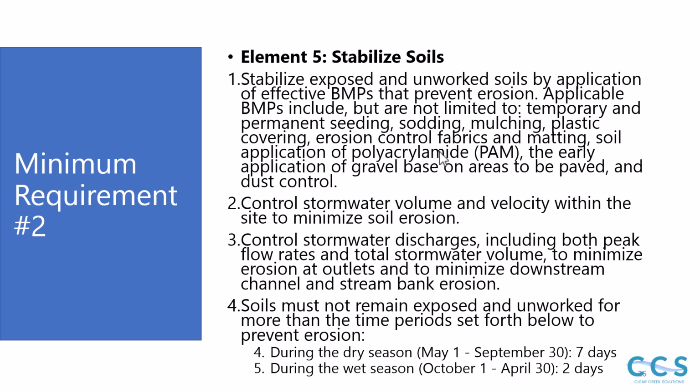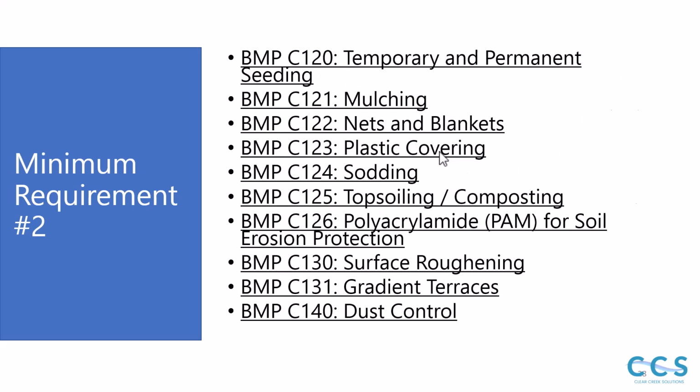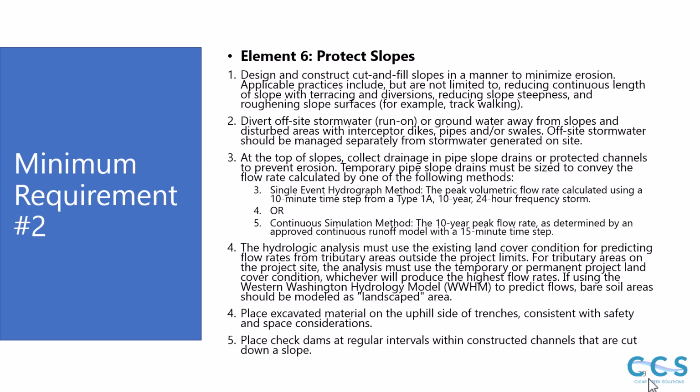Soils must not remain exposed and unworked for more than the time period set forth below. During the dry season, May 1st to September 30th, 7 days, and during the wet season, October 1st to April 30th, 2 days. Stabilize soils at the end of the shift before a holiday or weekend if needed based on the weather forecast. Stabilize soil stockpiles, minimize the amount of soil exposed, minimize disturbance of steep slopes, and minimize soil compaction, and unless infeasible, preserve the topsoil. And there's a list of applicable BMPs there for that element.